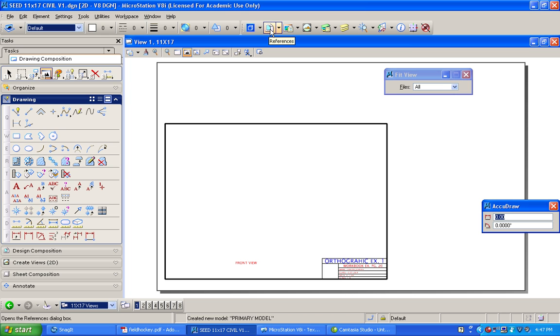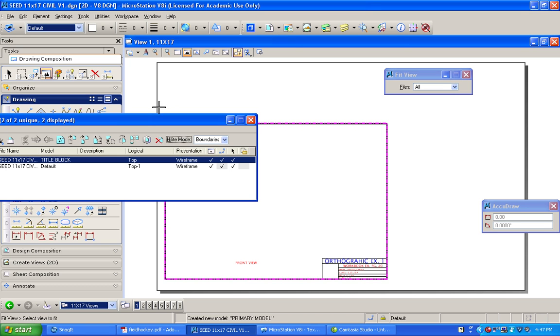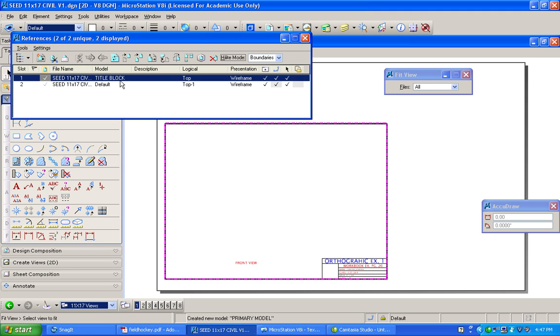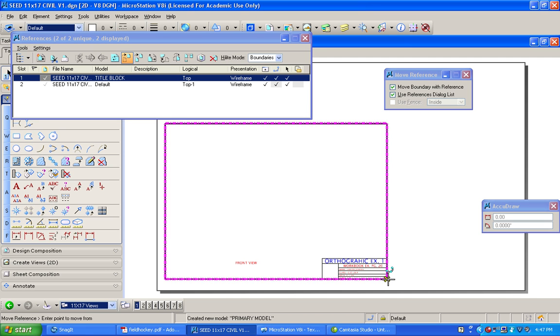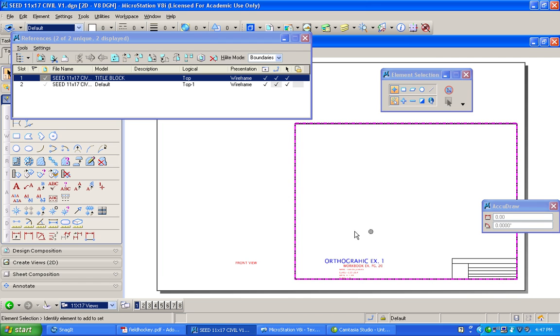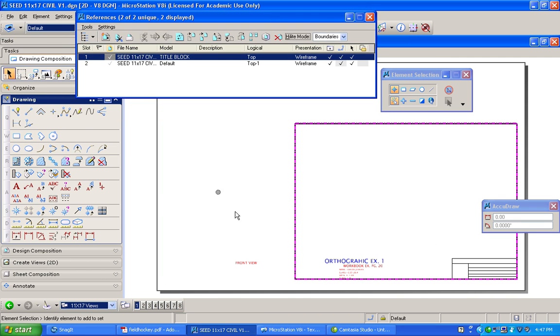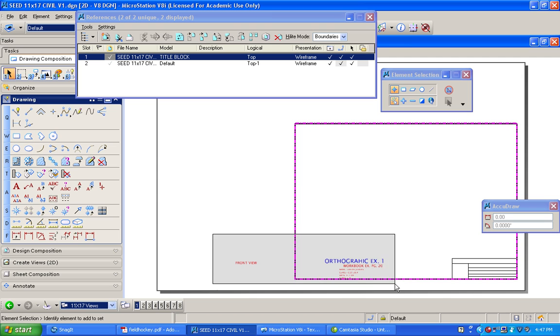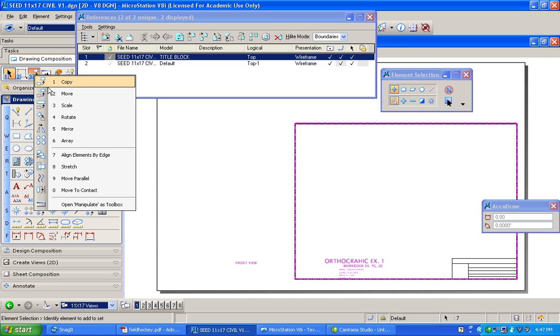We're going to take that title block down to here, right about there. You notice the text didn't move because that's part of the active sheet file, so we can take our selection tool, drag through that information, go to 3-2, move, and just move it roughly into the right space over here.